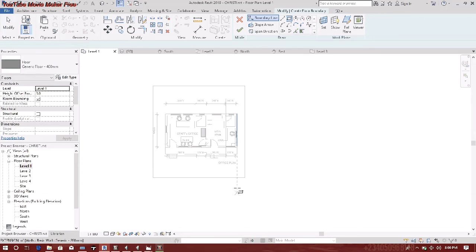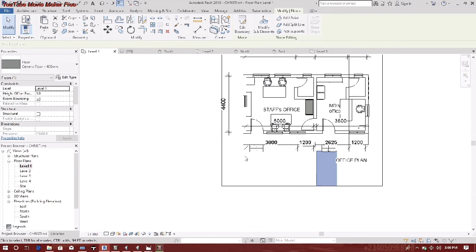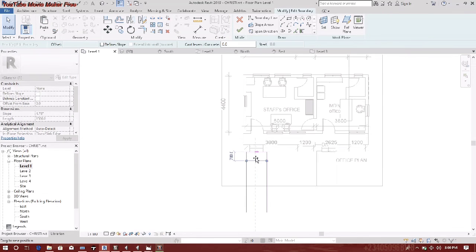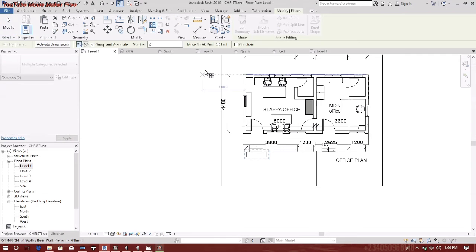So how do you do walkways? You do it the same way you do your floor. So you come here, then let's say we have this like this, then that is that. Then if it is the other type of walkway, just duplicate this, double click, then make this 400. Click on OK, then use the array button.